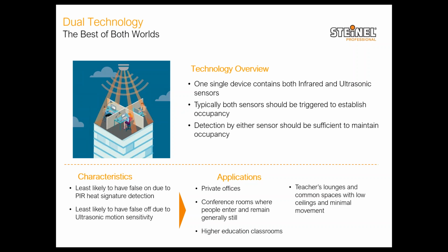Some of the applications for this are private offices, where you're sitting like behind with your back to the sensor, two big monitors in front of you, those kind of situations that you're not giving the sensor proper line of sight of your movement.